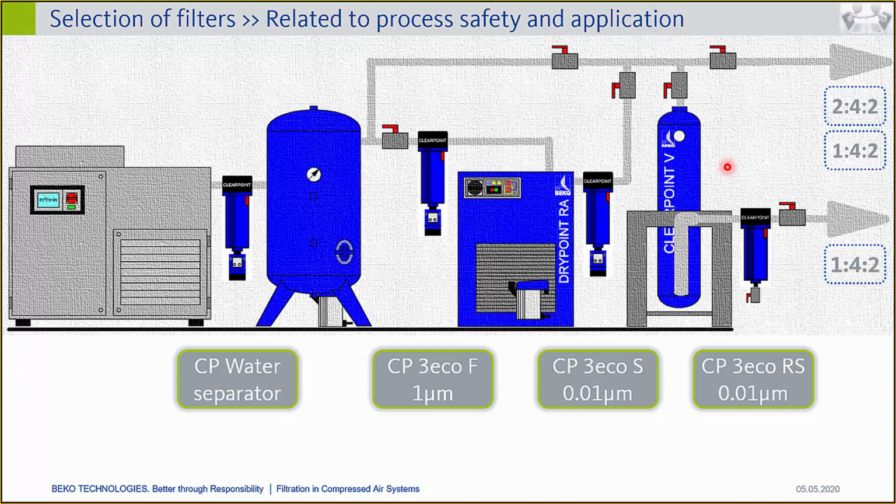You could generally say that upstream filters, which means the filters preparing good inlet conditions, should be placed as close as possible to the next treatment process. This is particularly important in this installation, where we just run the fridge dryer upstream of the activated carbon tower. Let's assume that the carbon tower is installed a bit further away, maybe because of the situation on site it needs to be placed in a different room, several meters away from the fridge dryer.